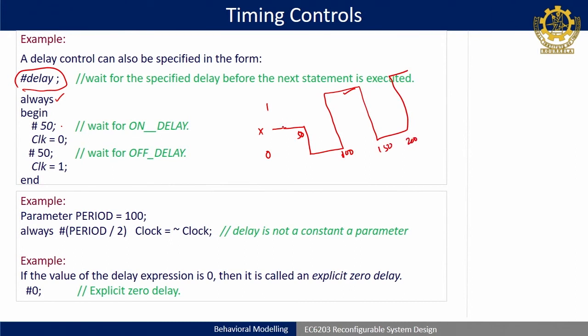As the initial value is not specified, it will start from don't care, but once it is specified it will come up with a valid state. The clock can't be don't care, it is an input, so it should be 0 or 1, or before this code you specify the value of the clock, like 1, then 1 to 0 can happen. Okay. So, delay can take this form also, meaning it will wait up to that many time units, and once it is done it will execute the next statement. It is not that you always have to specify it in a particular statement.